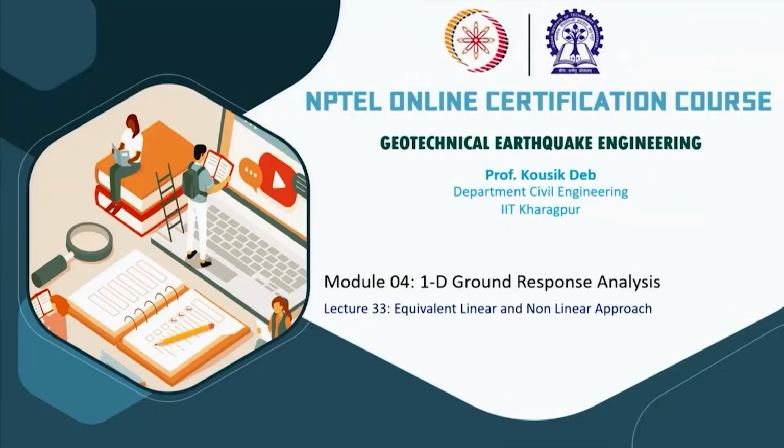because in the linear approach you can see that the shear modulus is taken as constant. It is not changing, because your strain or shear stress is a function of z, I mean depth, and the time. But as a uniform soil is considered, here the shear modulus is taken as constant throughout the depth, and it is also not changing with time. So it is constant, it is assumed here.